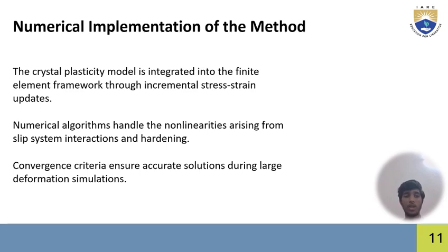The CPFEM is implemented in the finite element framework through incremental updates of stress and strain at each element, because of non-linear interactions among slip systems and hardening behavior. Numerical algorithms must be robust and iterative. Convergence criteria ensure that the simulation remains accurate even under large deformations. This step essentially connects theoretical crystal plasticity equations with computational simulation.